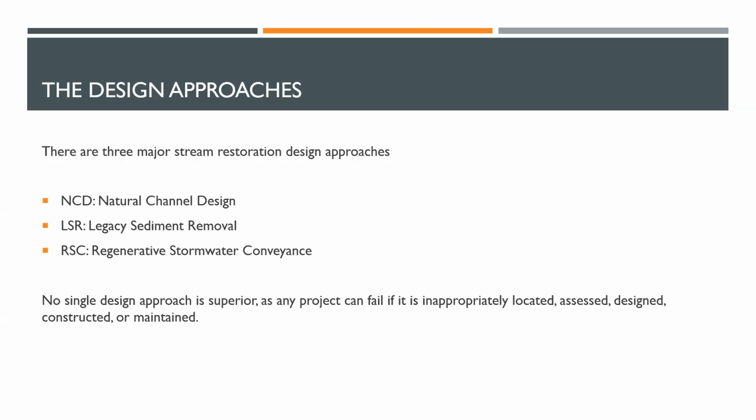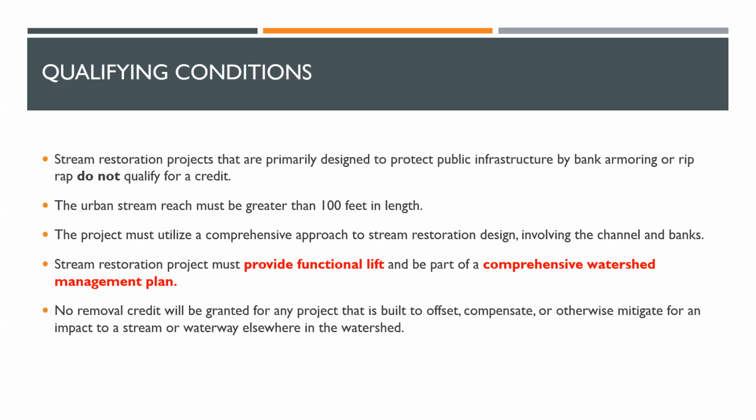Legacy sediment removal works well when you have a really wide floodplain area to work with, but we're seeing more and more application of those approaches as folks tend to shift in the last couple of years towards really realizing how important and significant that floodplain reconnection and the hyporheic exchange is, whereas I think past approaches were a little bit more zeroed in on that prevented sediment.